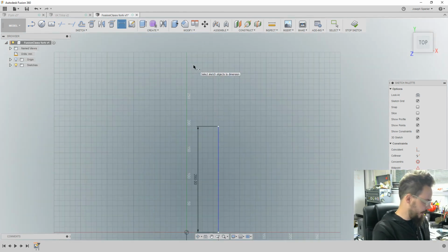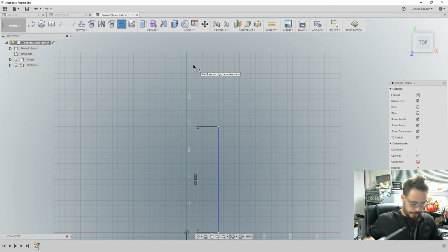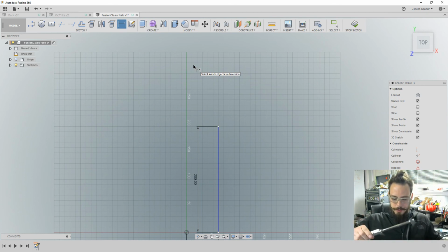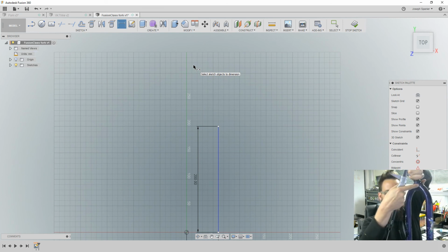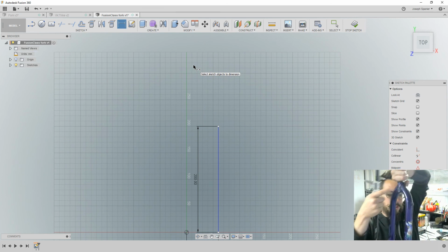And then the next step is if I take my calipers and I make a scratch in my beautiful paint. These are going to be painted lime green in their final life, so I don't really care what this awful purple fairy paint looks like. I'm going to eyeball the center line here from the top of my 200 millimeter line. It looks like it's about 95 millimeters to the center of the pipe right here in this intersection.